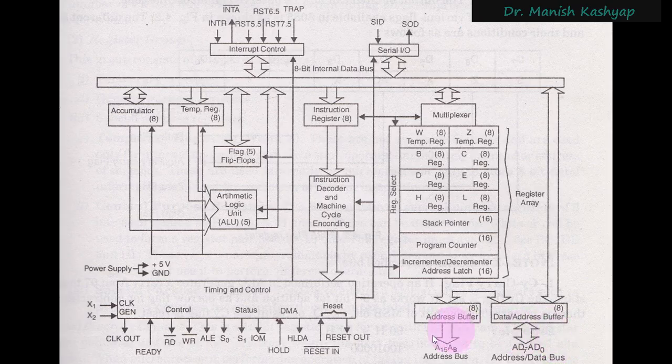So similarly, these address and data bus wires are available, which are coming out of the microprocessor, and they can be connected to various things in various types of connections. So that's what we are going to see today for connecting the input output devices in the two modes, that is the input output mapped input output or the memory mapped input output, right? Memory mapped input output does not require a separate discussion, because we already know that whatever is the memory location, if you are using a memory which is lower than 64 kilobytes, then for the remaining addresses you can connect input output devices there, right? So primarily we are going to discuss the input output mapped input output, and then in the end we will make a comparison between the two schemes, right?